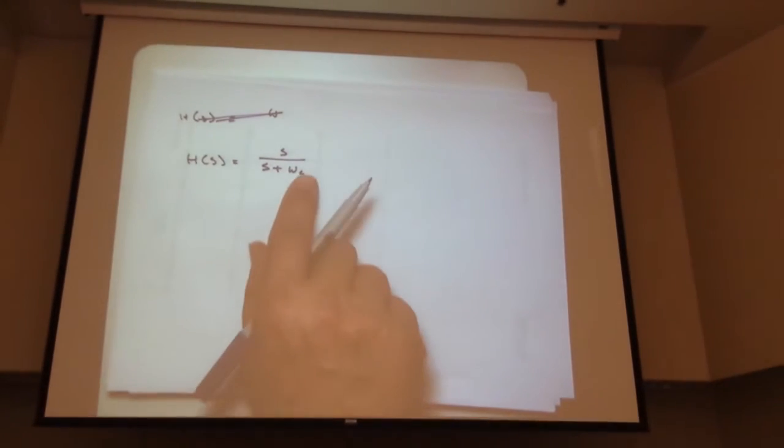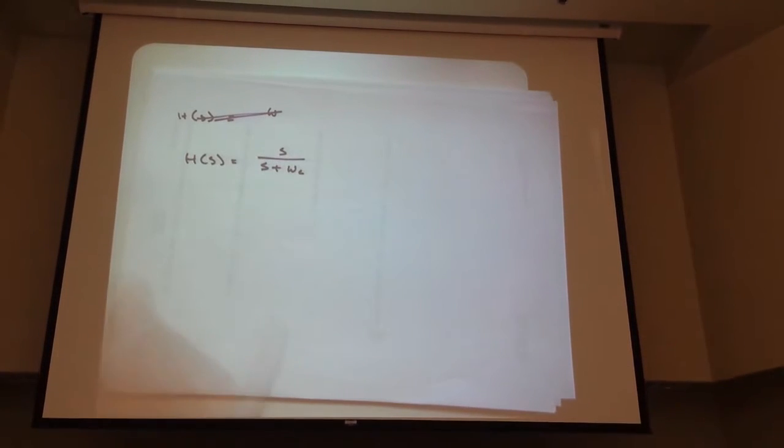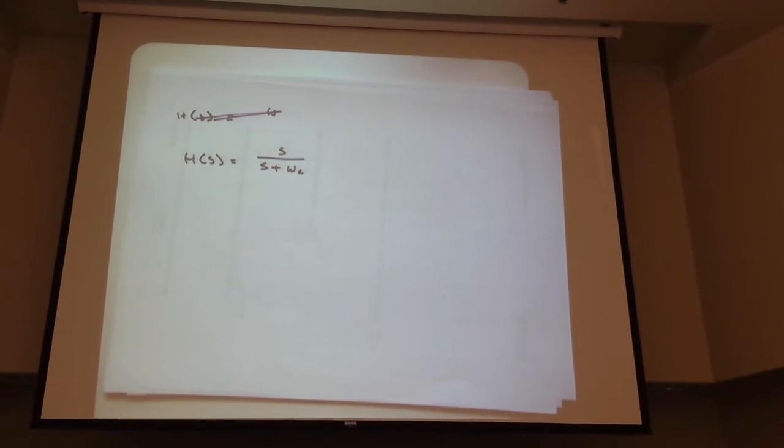So every pole has a minus 3 dB correction. Oh, every real pole. When we underdamp, then we don't look at that anymore, we look at the damping ratio.